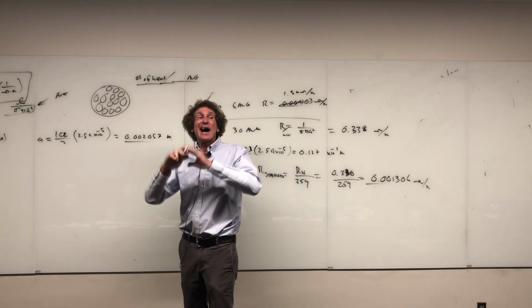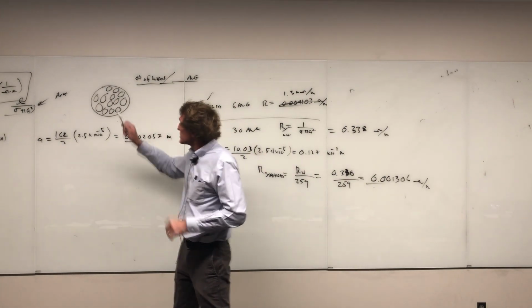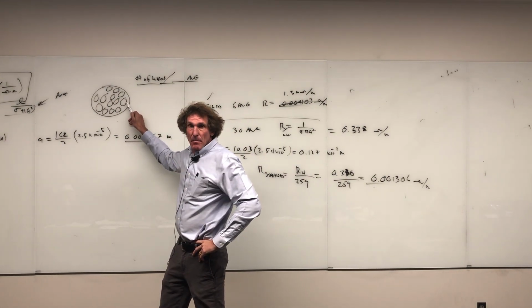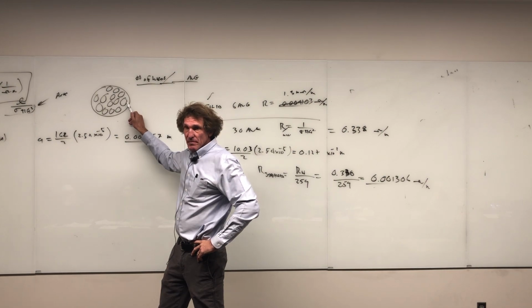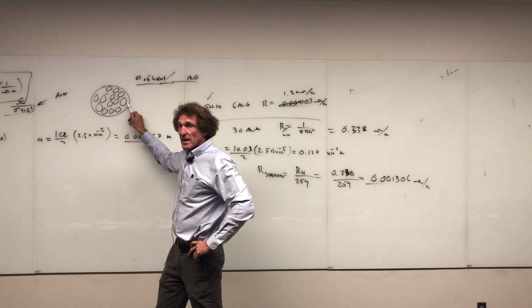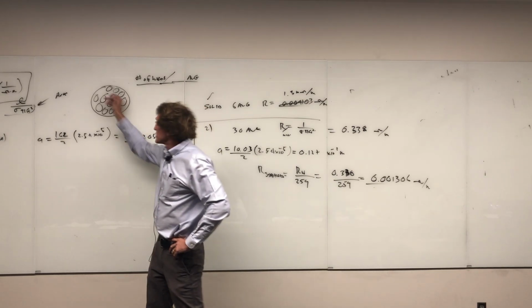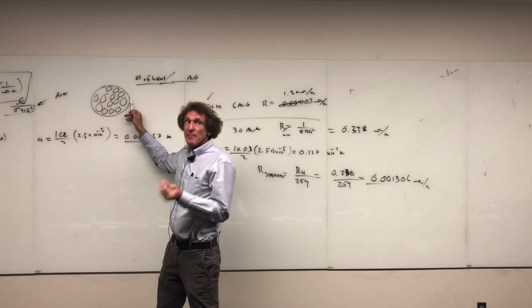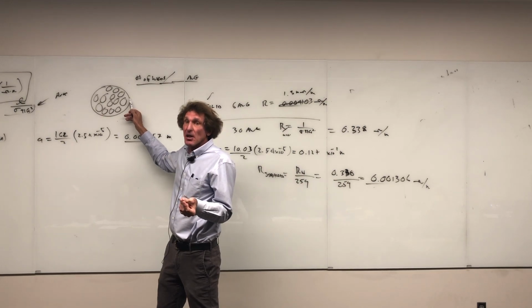When you're at a high frequency, the skin depth effects may or may not become pronounced. Remember, skin depth has to be of the order of the actual radius before you start worrying about AC resistance, right? Now, if it's solid, it may be a high frequency problem, follow me?